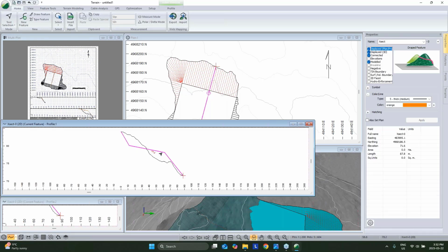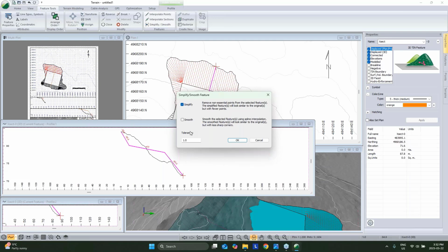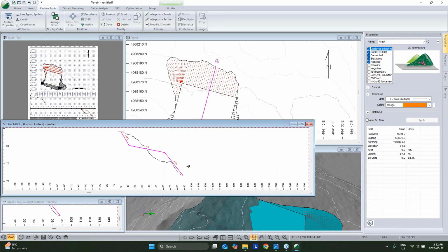And if I wanted this to lock in the geometry of the model that it's sitting on top of, I can turn elevations back on. We can see our cut and fill slopes. And here there happens to be an extra point up at the end. If we wanted to simplify this section feature that we're running with, we could simplify it to remove any extra vertices. So we've got a section.